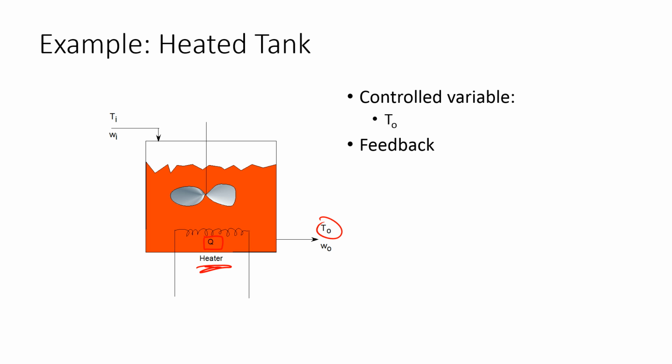And so I'm just going to draw the temperature transmitter first. This is a thermocouple or something else that is able to measure the temperature that's coming out of our reactor. Okay, and then I'm going to have another circle here, and that's going to be a temperature controller. And that is going to be adjusting the heater rate to the reactor.